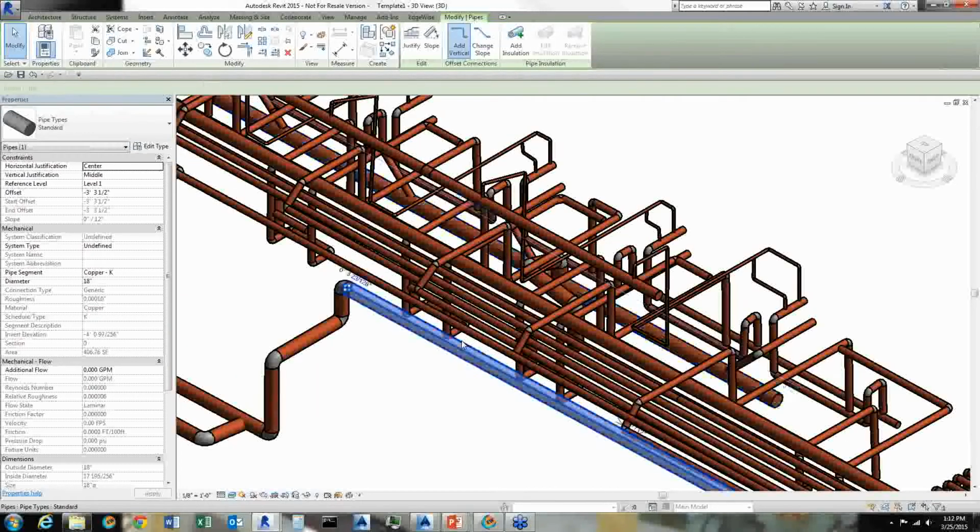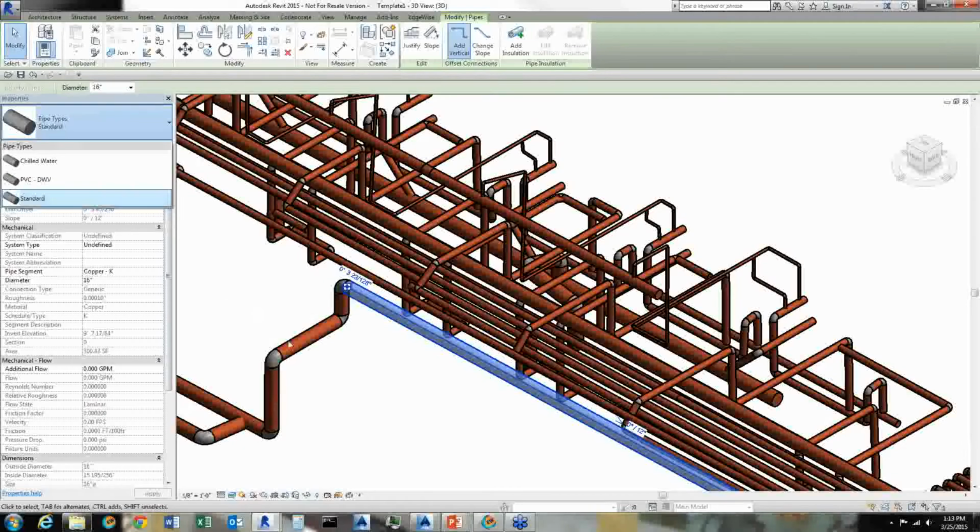The basic functionality is we would use EdgeWise to automatically extract these pipes, catch any pipes that were missed, and complete the model, and then export to Revit using our Revit plugin. And of course, all of these objects come in as fully functional Revit objects.